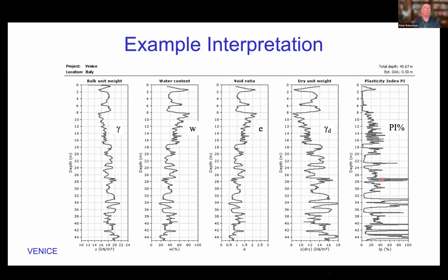But about 15 years ago, we developed a correlation that said you can actually estimate the unit weight based on the soil behavior type. So the non-normalized soil behavior type chart, you could estimate unit weight. And so we added this to the program. So here's a plot of the estimated unit weight. And you can see on average, it is about 18 at this particular site. But of course, it's lower near the surface and gets higher as you go deeper. As it gets denser, the unit weight increases with depth.